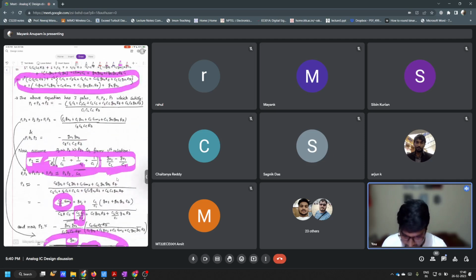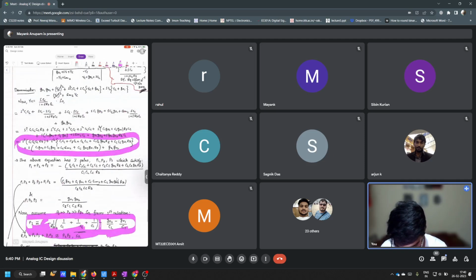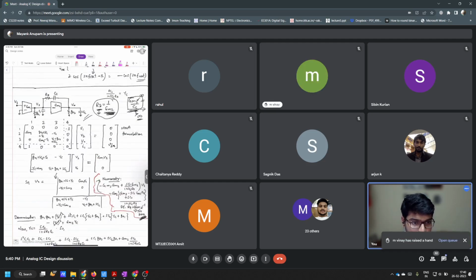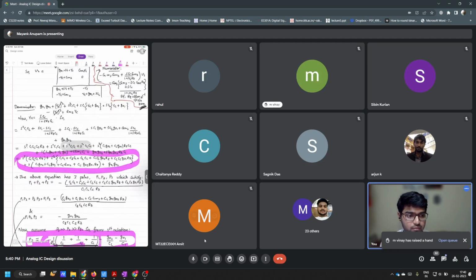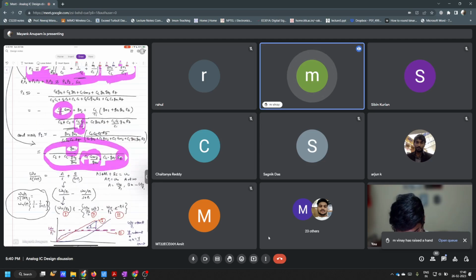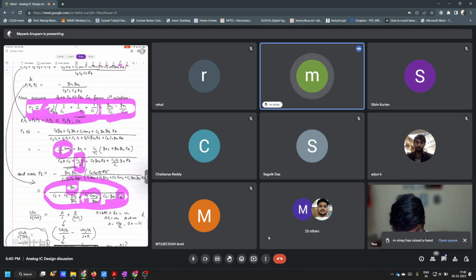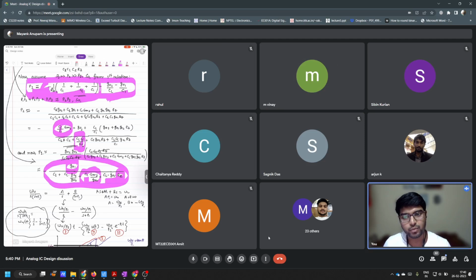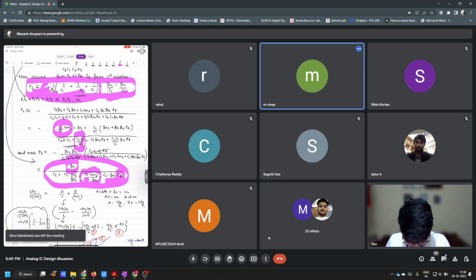Okay, so I will share this calculation with you all, but I will advise you to do this calculation yourself also. Yeah, someone has raised the hand. Sir, P1 will be affected by that feedback factor, sir. If instead of unity feedback, I connect the R feedback, then the P1 open loop systems will be affected, sir. Now why? It should not be affected. Pole p1 p2 will not be affected, only omega u loop will be affected. Yes. Okay. Thank you, sir.